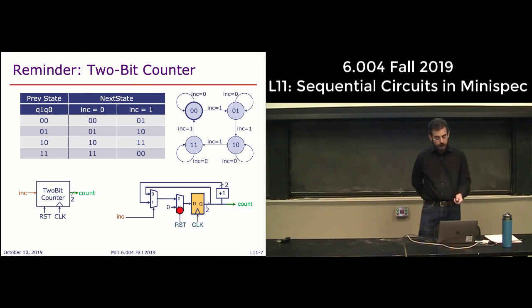And so we have some reset circuitry because we want this to start in state 0,0. So what we're going to do is have a reset mux here, and then if reset is 1, we're just going to store 0 in our register. And then once we're not resetting, we have yet another mux here. That's the write enable signal, or the write enable circuitry. And so we're going to update this register with one of two values, right?